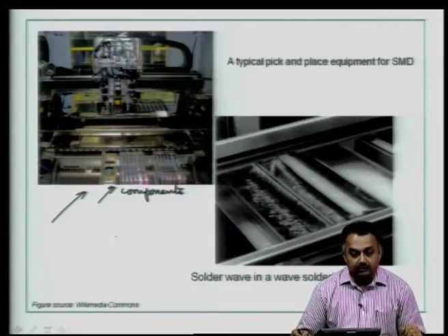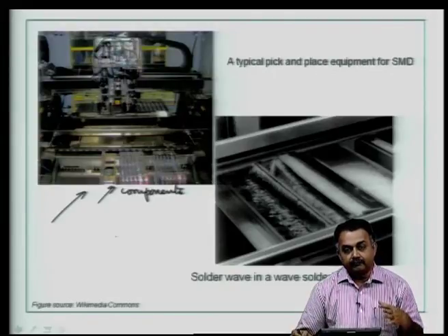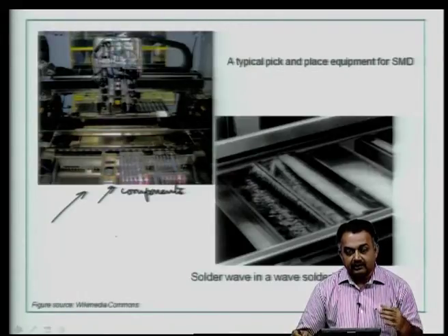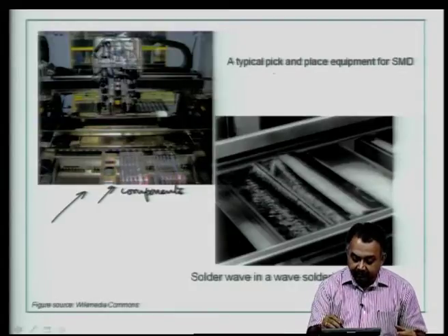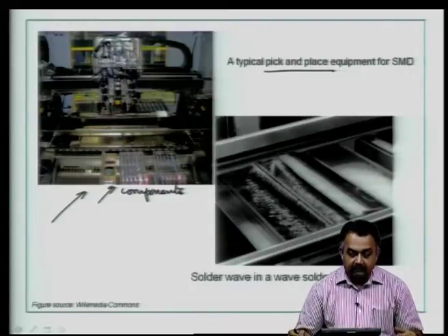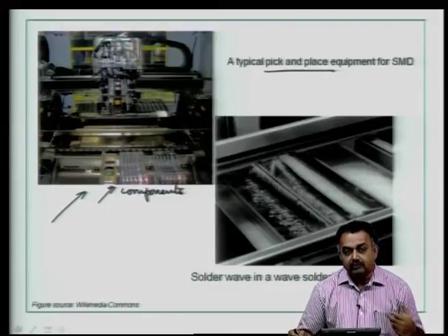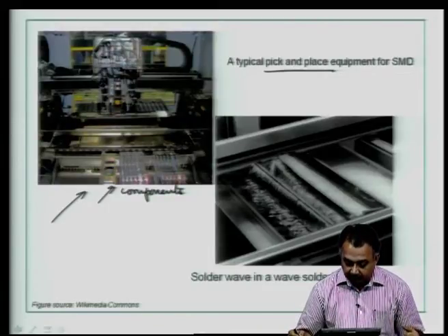So, you can expect that when you use a reflow soldering process, you first dispense the solder paste, and then the next step is the pick and place process, typically using high volume, high end machines. You can also do it manually for prototyping boards.